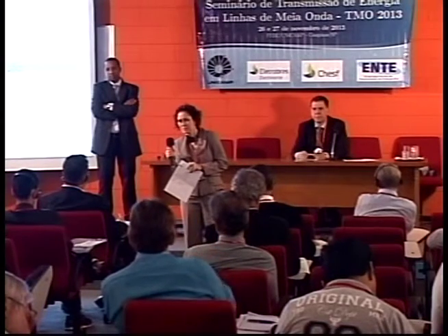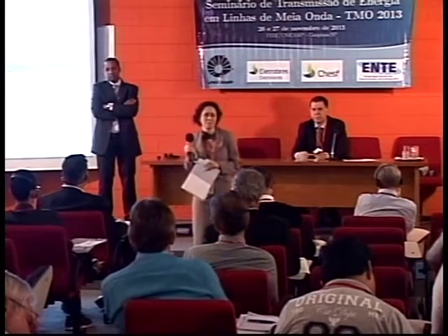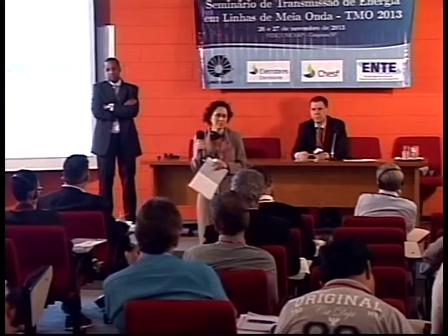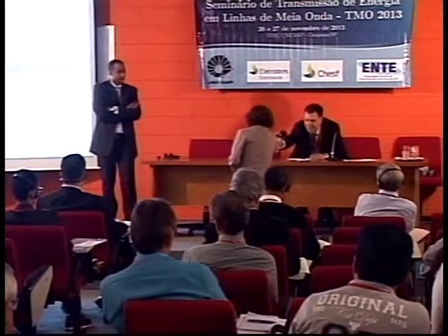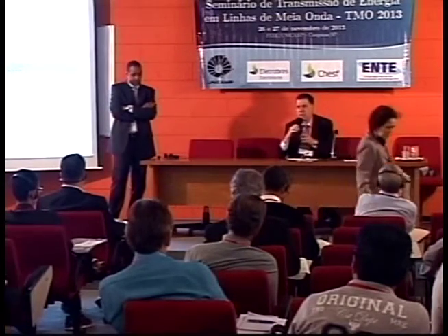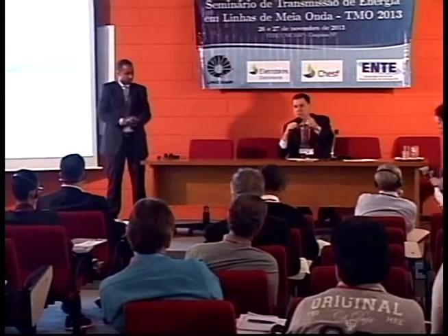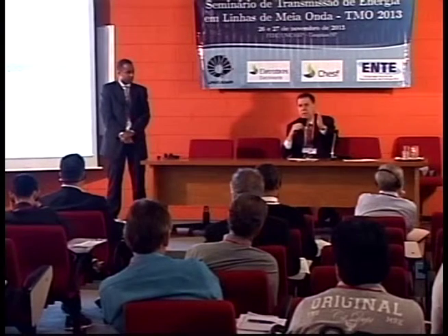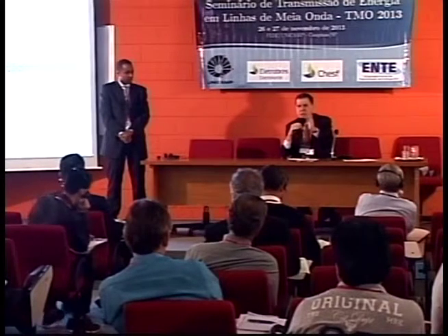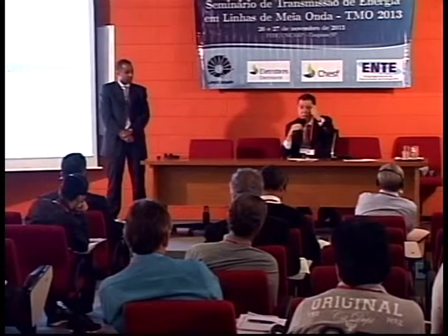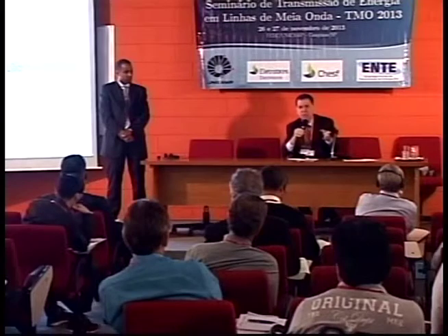I don't know if our foreign guests have some additional information about this criteria of choosing the application distance for kilometric faults. Just to complement you, Lima, you are right. For the kilometric fault, for specification purposes for the circuit breaker, you do this from 1 to 5 kilometers to define the most critical one between the growth rate and the current value. But our purpose here was not exactly this one.